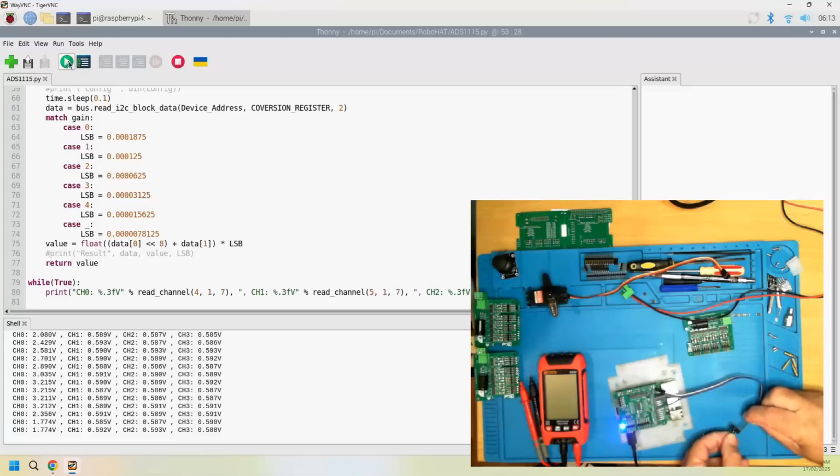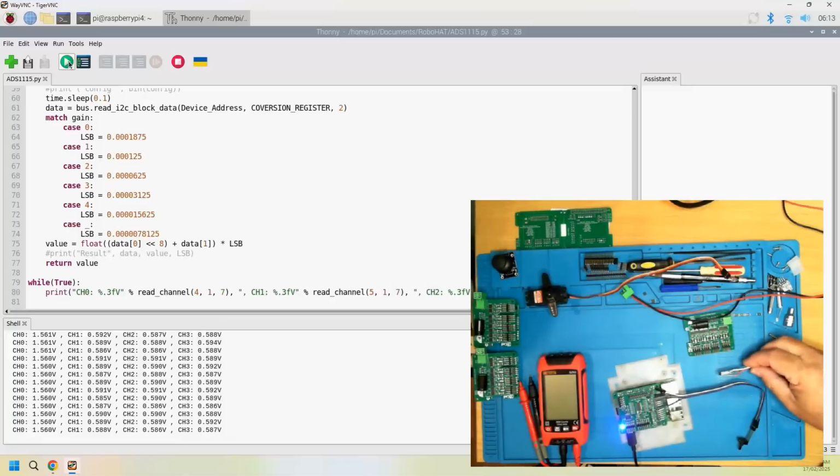Okay, so things that we can use that for include connecting it to a hall sensor. This is probably not the best example hall sensor, but the ones that are used in, say, the InMove robot hand fingers are an analog output, and we can actually read the value coming off that to sense the strength of the magnetic field that it's detecting.